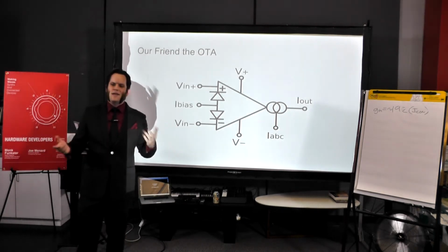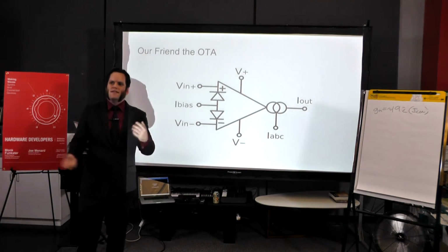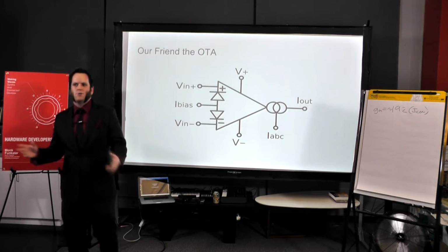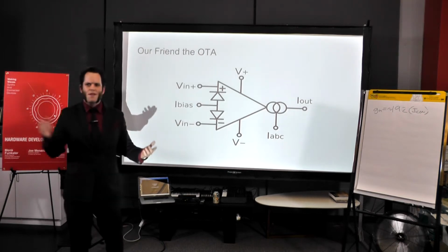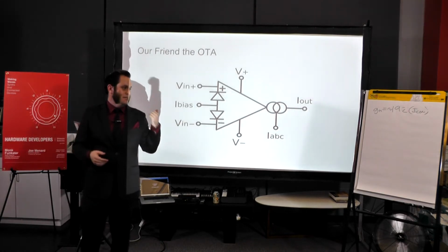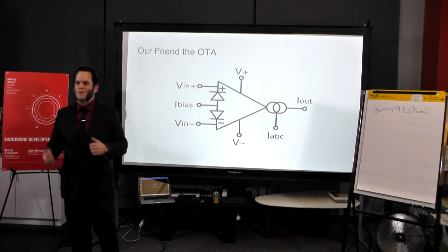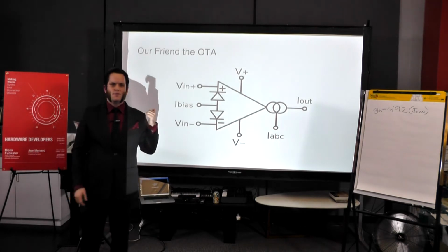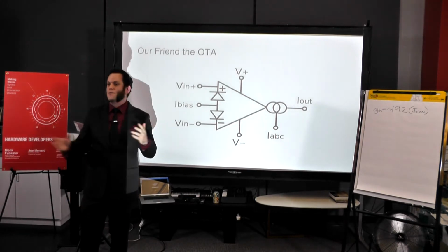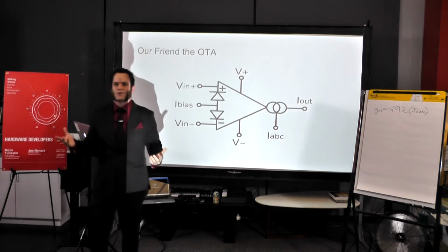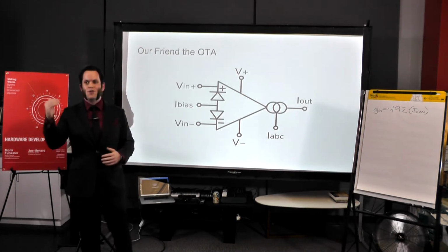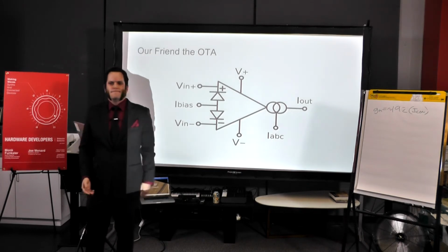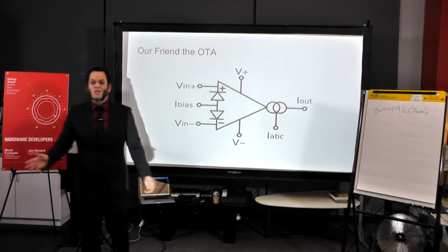It serves as the basic component of most everything in the classic Moog, Buchla, EMS, whatever analog synthesizers. Bob Moog especially loved these, like the CA3080 and the CA3082, and tried to put them in pretty much everything. I should mention this is also absurdly temperature sensitive, and a lot of the really early analog synthesizers had heater cores to bring them up to a known stable good temperature, because everything worked better at like 50 degrees Celsius.